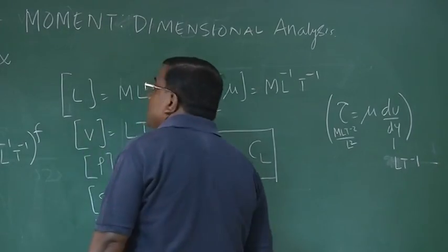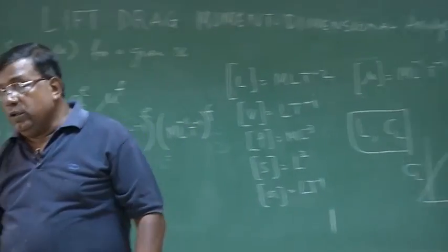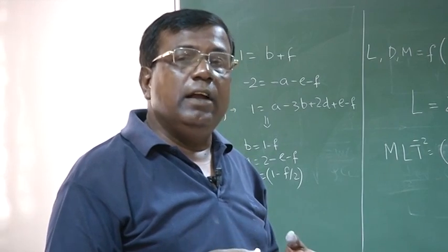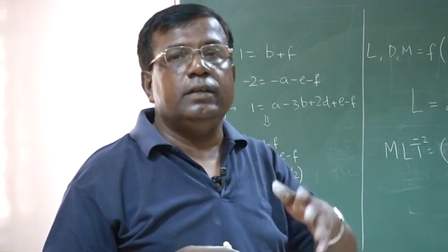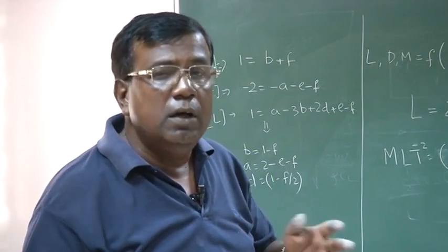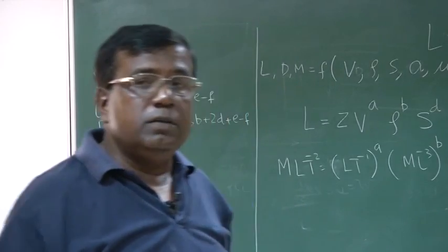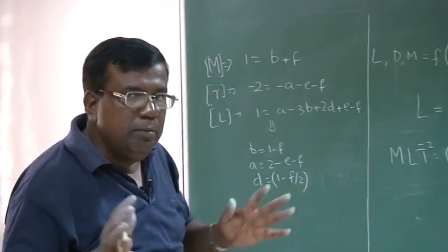For example, so far we have been talking about CL and alpha, and we are talking about CL as a function of alpha. The question now asked is, for a given alpha, taking into consideration the flow and body interaction, what is that so-called complete description which will ensure that CL at a given alpha has been modeled accurately, keeping in mind there is a flow over the surface, there is a boundary layer, there is a viscous force, the viscous boundary layer will be redistributing the pressure distribution, all these things. And if it is supersonic speed, then there is a shock wave. The shock wave will also alter the pressure distribution. In a holistic manner, can I think of modeling CL for a given alpha? That is the basic question.